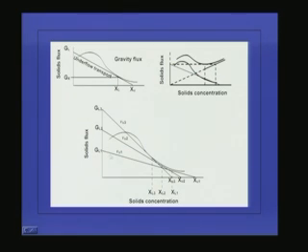For different concentrations we get different points. For Xu1 you get GL1, for Xu2 you get GL2, and for Xu3 you get GL3. These GL1, GL2, GL3 are known as the limiting solid flux, that is the maximum flux we can get for that underflow concentration.